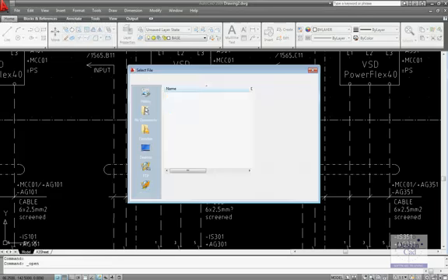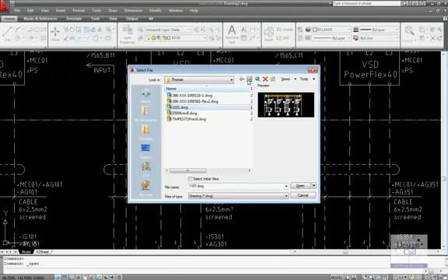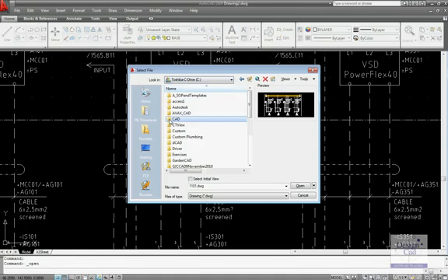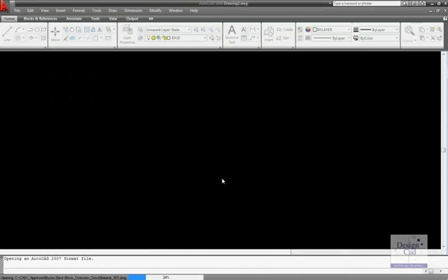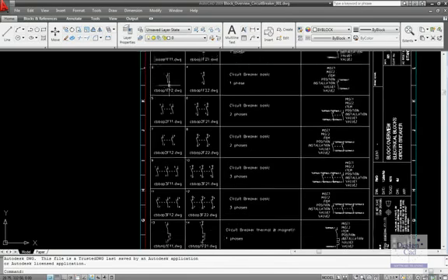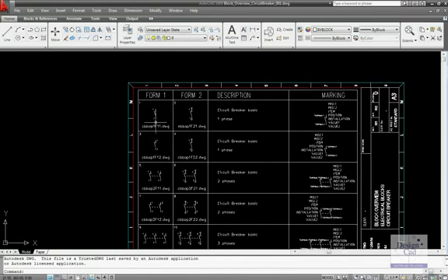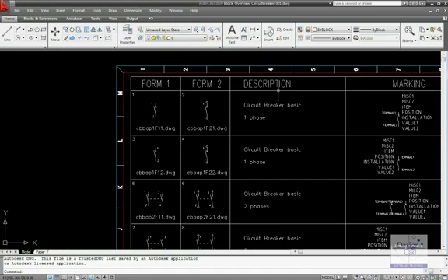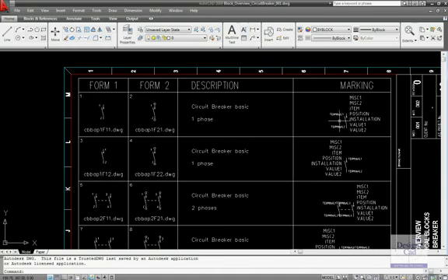If you did want to check the name of an individual drawing, go back again to the CAD folder on the server and go into approved blocks, into electrical, and open up, let's say, the circuit breaker master drawing, and here you'll notice we've put individual examples of the blocks here, a description of them, and over here is the thing you just saw in the thumbnail that we brought in, the position of the individual attributes.